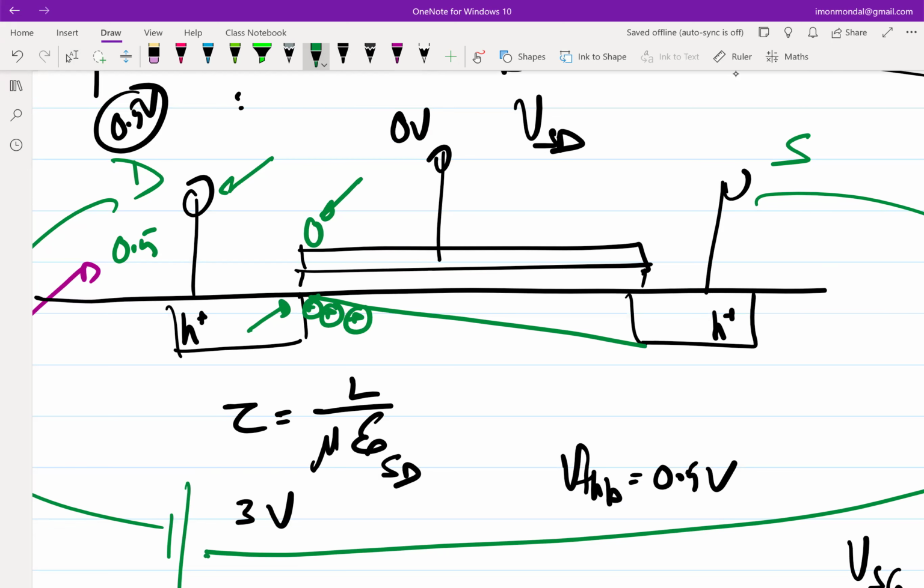That immobile charge is highly resistive, giving you a very high resistive zone. So any extra voltage that you apply will drop across that small sliver that is getting exposed. So essentially, for all practical purposes, the potential difference that the mobile charges are seeing remains the same. I didn't want to get into that because it goes slightly deeper into device physics, but that's essentially what happens.